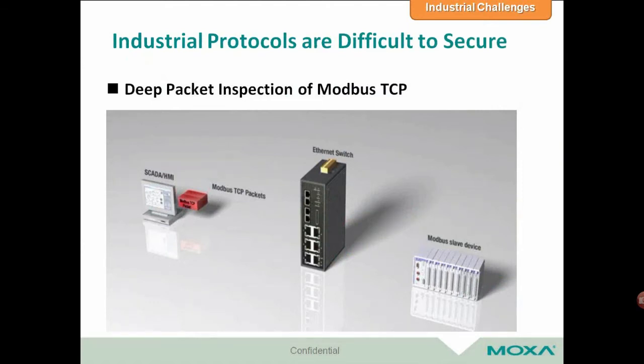While enterprise-level security devices typically filter packets based on IP address or port, industrial devices need to be able to look deeper into the packets of data to the commands embedded in the application layer in order to filter potentially harmful data. They also need to be able to do this without introducing delays in transmission that could cause a malfunction.